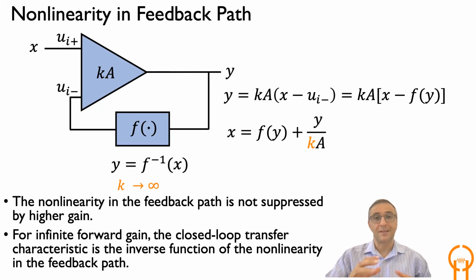So this is now applicable not only to scalar transfer functions, but also to nonlinear functions. So if you put a nonlinear function in the feedback path, you can actually invert it. It's quite a useful tool if you want to generate some nonlinear behavior.